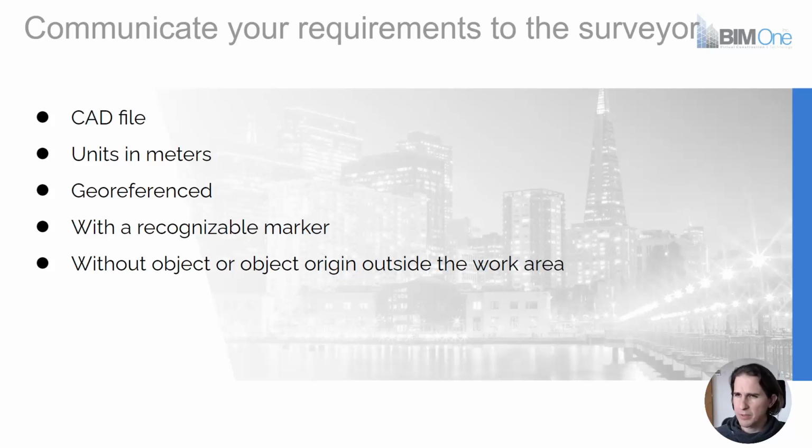Right now, when I'm talking about that, I'm thinking very hard about the CAD files. Usually when the origin of a CAD file is somewhere very, very far away and something is drawn next to it, that's where you get the dancing line issue. So that's another point that we'll talk about in the next webinar, where we'll show you how to deal with it.